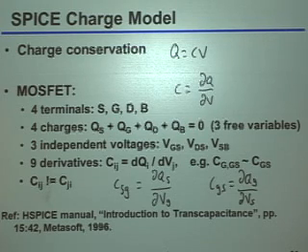And usually we'll assign some percentage of that charge either to the drain side or to the source side, right? However, if we change the voltage at the drain, to zeroth order at least, that doesn't have a big impact on the charge that's actually seen on the gate side. And so because of that, there's an asymmetry there. That's why, indeed, CGD may actually be very different than CDG. Is that clear? Okay, great.